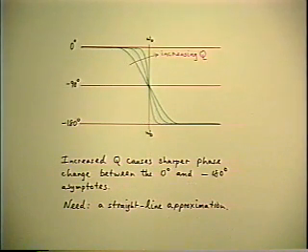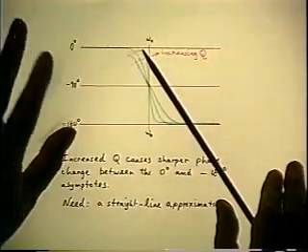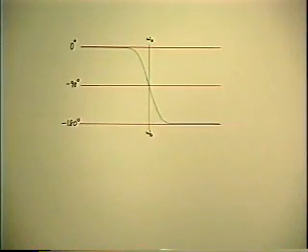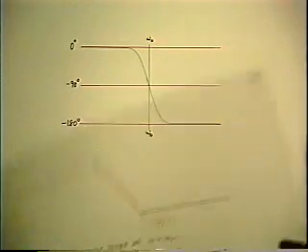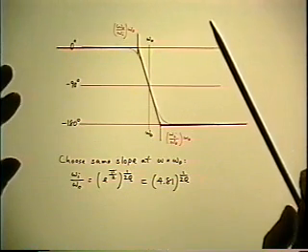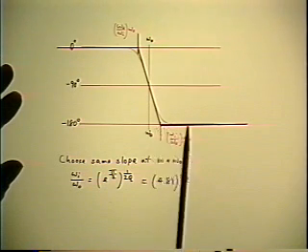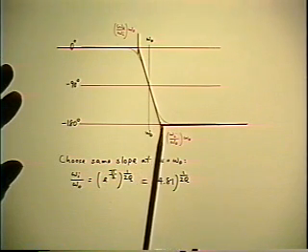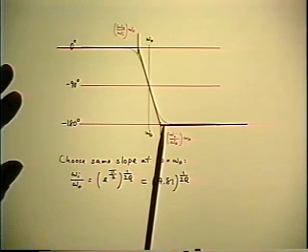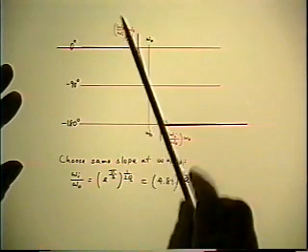Now we can approach that in the same way that we did for the single pole function, except that there's not a unique line this time, because we're going to get different lines for different values of Q. But a starting point, once again, would be to find the slope of the actual phase graph at the symmetry point and extrapolate that slope until it intersects the other asymptote, and then by geometry find out what the value of that frequency is. Then, when you want to draw the straight line, you just mark off that frequency on the horizontal axis and then draw your line.